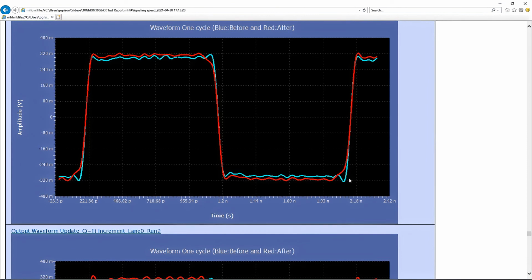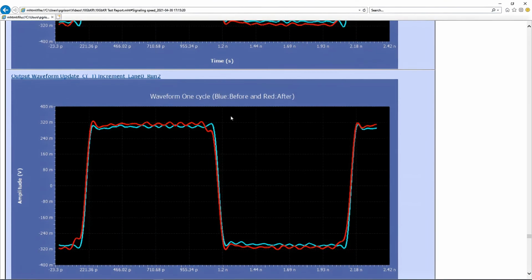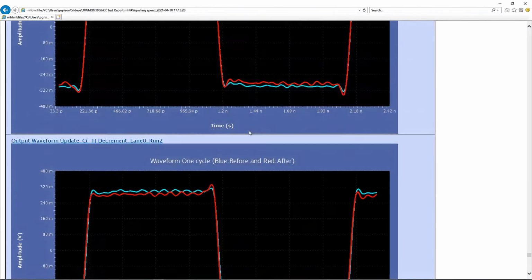And if you look at the following rising edge, you have the same effect. The last 0 transmitted before the first one will get a slightly higher amplitude. And the purpose of that, again, is to help balance the signal at the receiver, so you get something which is the best possible at the receiver. So the whole purpose of pre-emphasis or de-emphasis distortion is to get the signal better at the receiver side, to account for the channel.